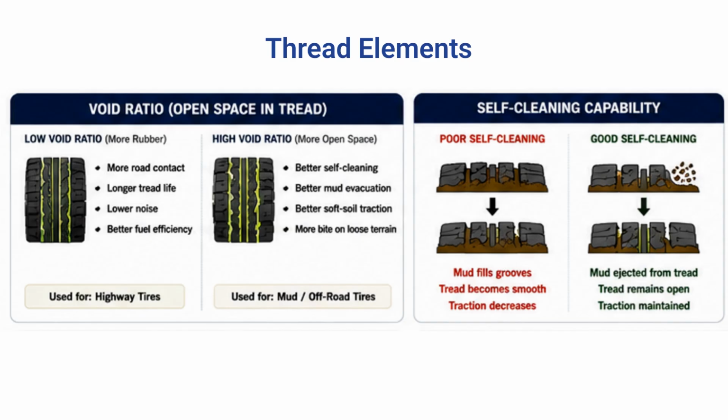Second is self-cleaning capability. When mud remains trapped inside the grooves, the tread surface becomes smooth and traction decreases. A well-designed open tread flexes and ejects the trapped soil as the tire rotates, keeping the grooves clear and maintaining grip.